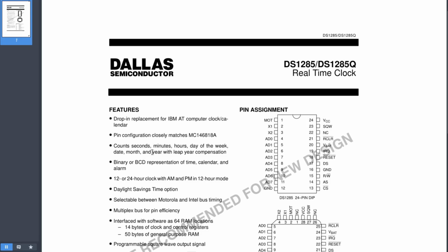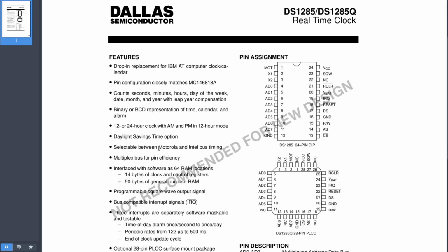It was equipped with more general-use memory, which was required, for example, for the BIOS settings and initialization, but it also reused some previously unused pins to connect the battery. The previous pins to control the square wave generation were deprecated, and instead pin 20 was now used for the battery plus and pin 16 for the battery minus poles.